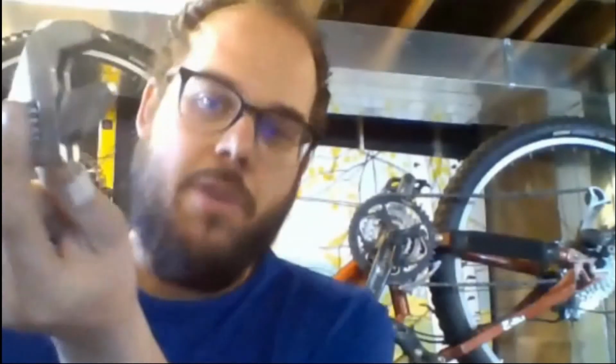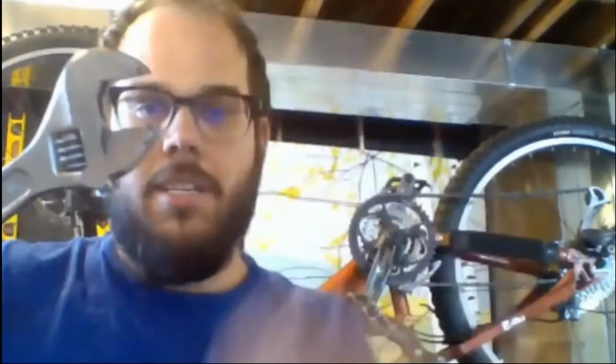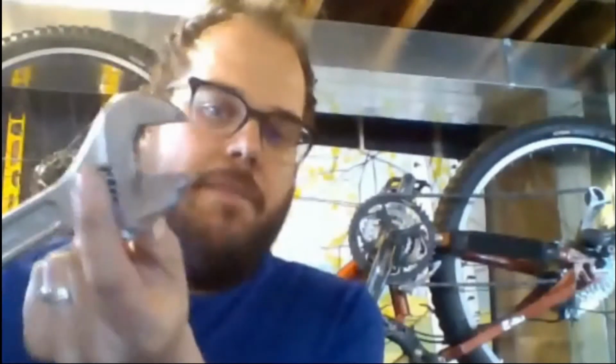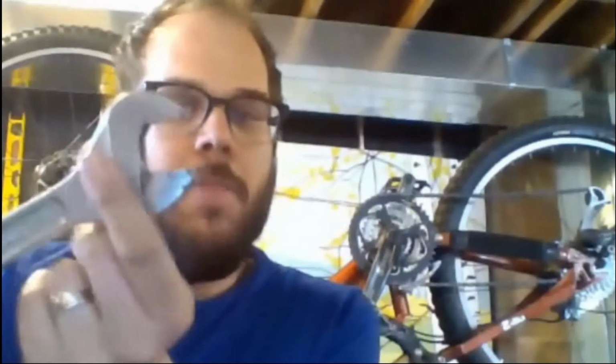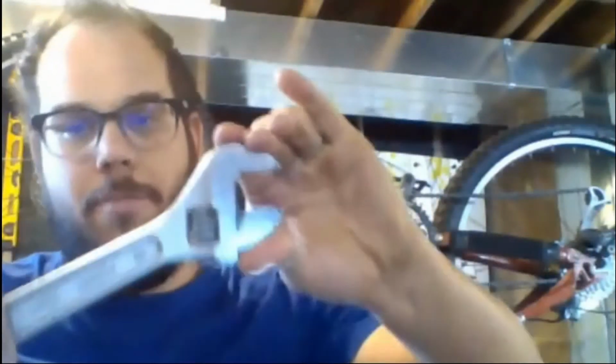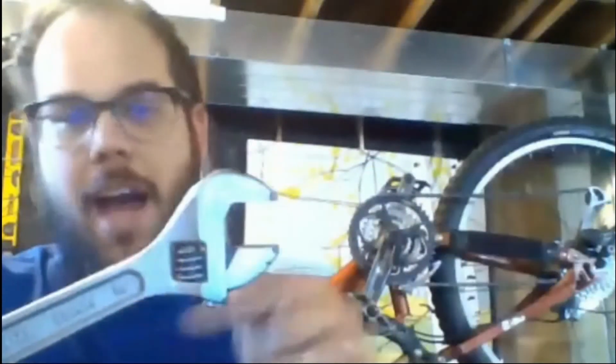I'm applying a force and a distance to this little adjusting mechanism, and that's applying a force and a distance to this. You'll notice that the way this is designed, I can apply a very easy force to make it open and close. But if I try to work it from the other end and make it close this way, it's actually impossible. I can't apply enough force here to get the other end to go backwards. And so this is kind of a deliberate design for this machine.